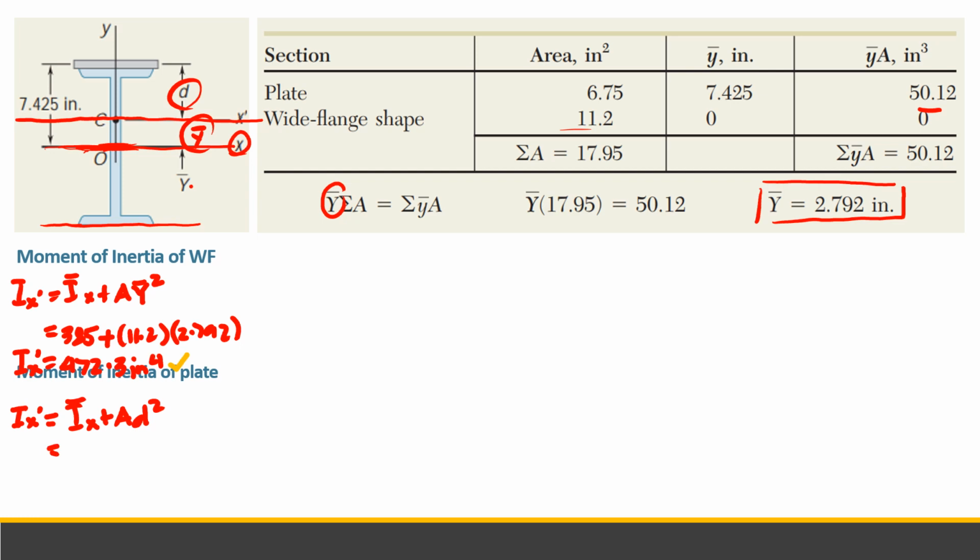So this is equals to, so sa mga properties kanina no ng common geometrical shapes, the centroidal moment of inertia ng rectangle is 1/12 base times height cubed, bh cube. So base natin is 9, h natin is 0.75 inches, no?